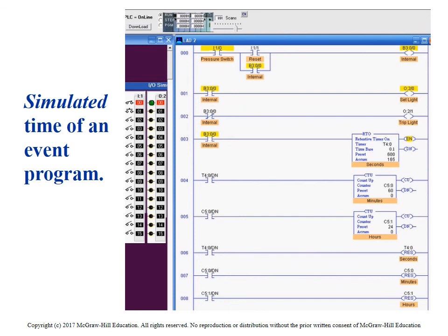I'm going to zip through this pretty fast. You don't have to watch this timer count to 600 and all that. So here we are, 599, counts to 1. As you can see, it triggers the done bit so fast you didn't even see it, and triggers the accumulated value of 1 here. So that's pretty much it for chapter 8.